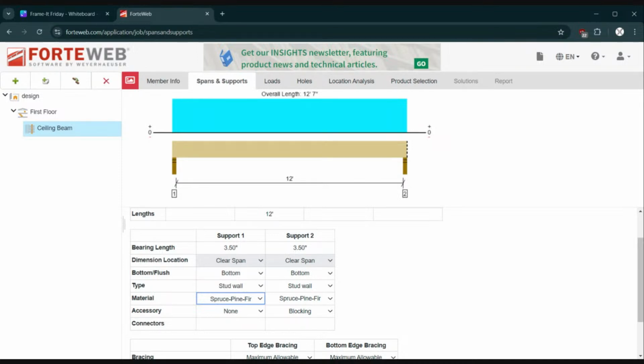So we're going to leave, if I was in Texas, I'd probably say Southern Pine because that's what most stuff is going to get framed out of. If you're going to use cheap Home Depot wood, you're probably going to use SPF because that's a much lighter wood and less dense. And it has a less compressive strength. So we could leave it as that if we wanted to be safe.